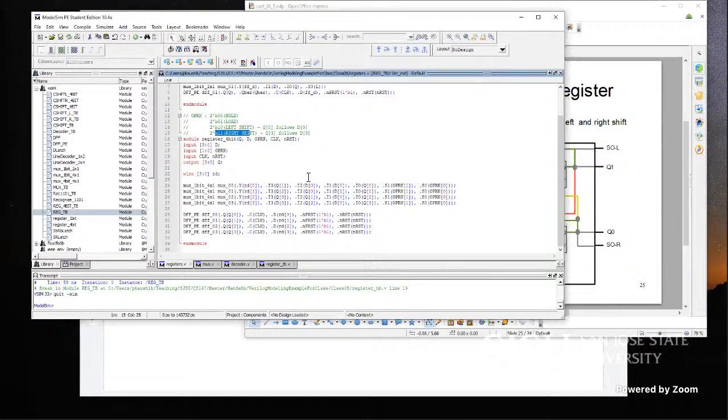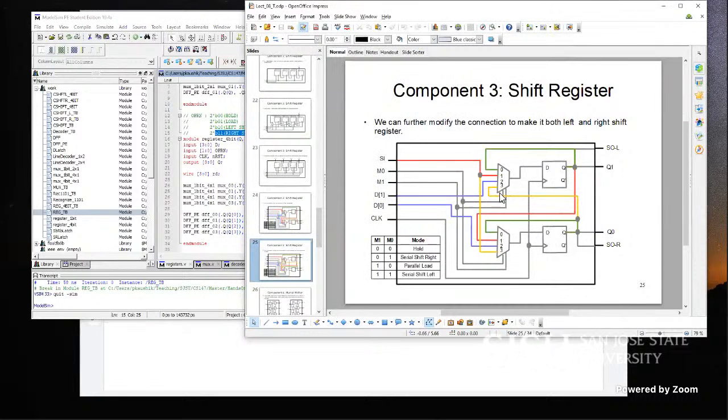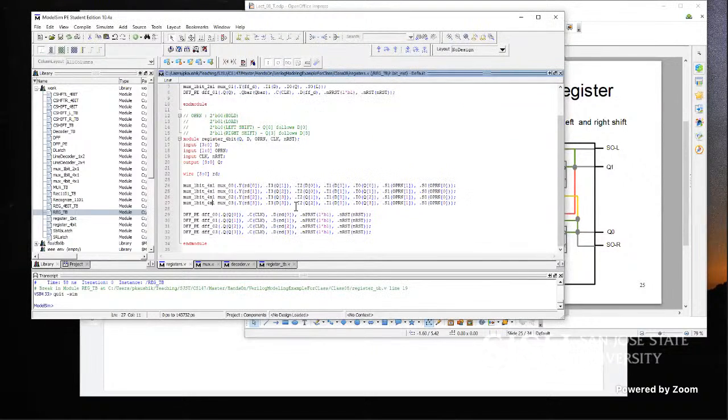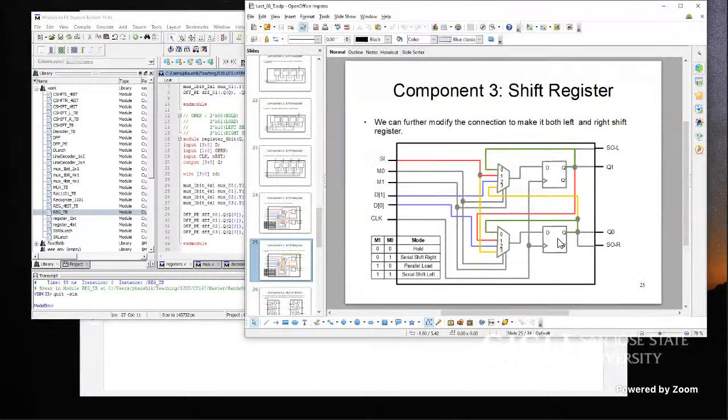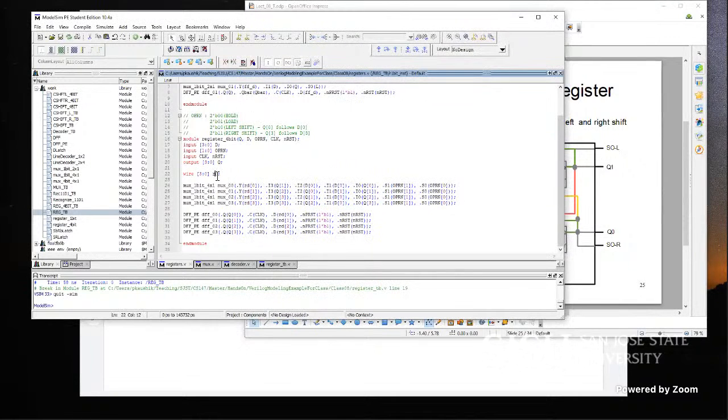And it's just a bunch of these top level, high level components, 4 multiplexers, 4 D flip-flops. We connected them accordingly to what we want to do. You see, by the way, each of these internal D flip-flops is connected to the output of the multiplexer, which I defined as a bus, the RD bus. And this RD bus is a 4-bit bus.